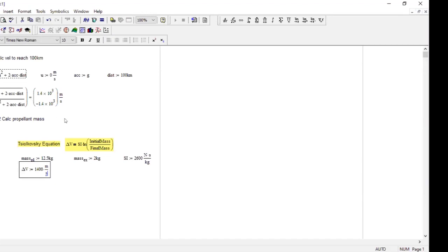So now we have to express this equation in a slightly longer form, and we need to express the motor mass in terms of the propellant mass. I'm going to say it's quite a reasonably high performance motor, and we're going to say that the rocket motor itself is 80% propellant. So it's got a mass fraction of 0.8. So 80% of the rocket mass is propellant.